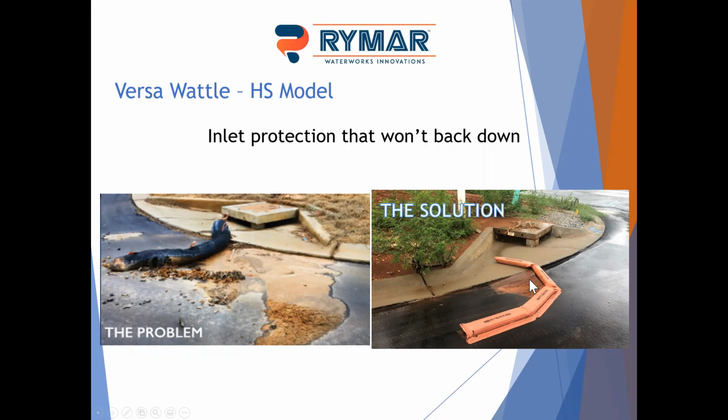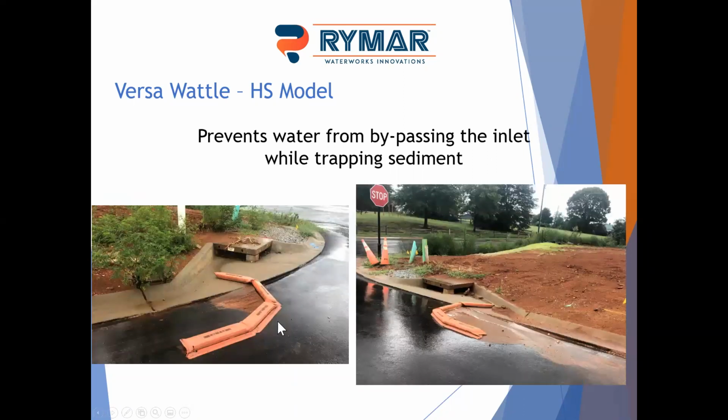So we had a couple of projects where they were using these, and they had long downhill runs, and the water was bypassing the boxes, going to the low point and blowing out the low point. And one place caused some really severe damage. It was like a 30-foot slope, and that entire slope got washed out, I believe, twice because of that. So we came up with this idea.